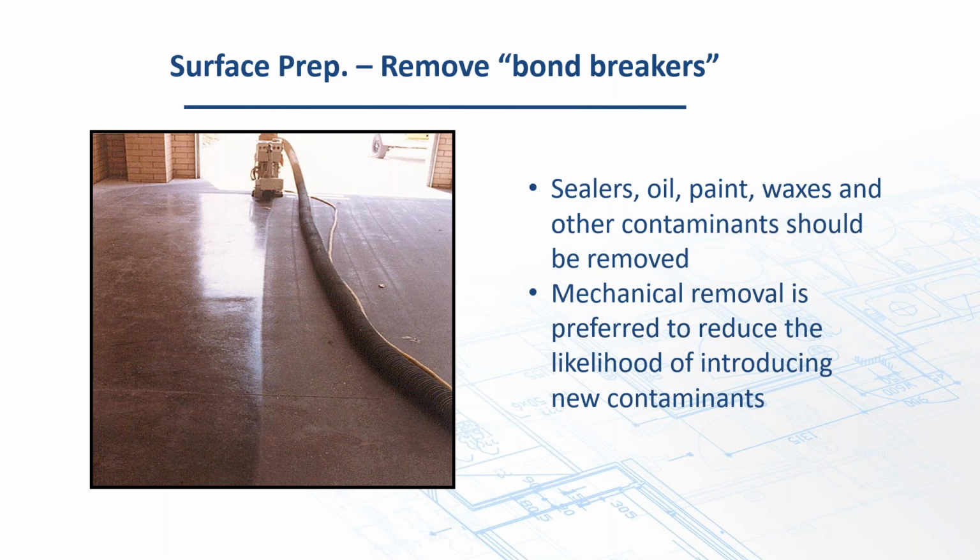I probably get a project in my office once every 2 weeks. It's like this, where it's penetrated so far they're going to actually have to scarify or remove a layer of the cement. But mechanical removal is preferred. Don't try chemically.